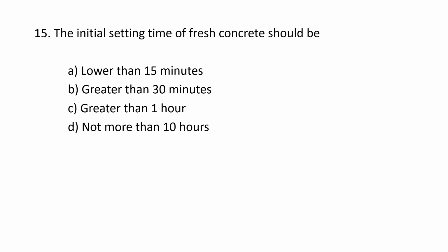Then the 15th question. For the initial setting time of fresh concrete, you should be very careful. They are asking about the initial setting time of fresh concrete, not cement. Because in the options you are seeing greater than 30 minutes, you will have a tendency to mark that option, but it is not cement, it is fresh concrete. For fresh concrete the initial setting time is greater than 1 hour. So the answer is option C. There is a chance that you will get confused between cement and fresh concrete. You have to be very careful. In cement it is more than 30 minutes, but in fresh concrete it is greater than 1 hour.